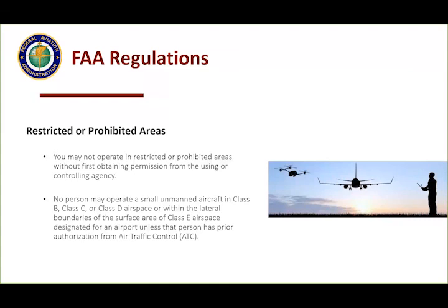Put in very detailed information about your service area, very detailed information about your drone, very detailed information about your lost link procedures, your flyaway procedures. I think it almost makes you a better pilot when you go through that application process.